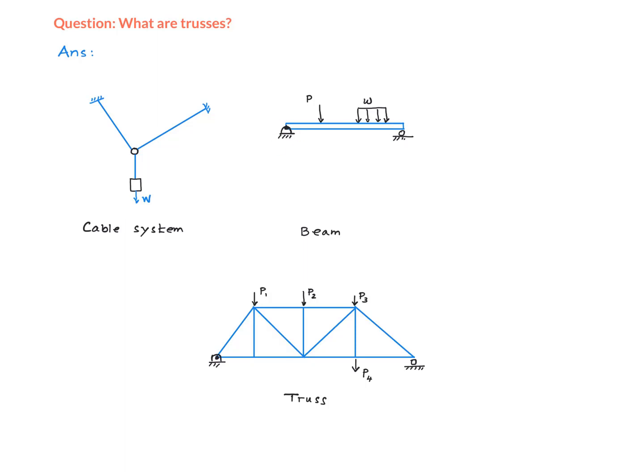To design the beam, we have to find the support reactions and the internal forces at all the points on the beam. We treat beams as rigid bodies, so as we go from a particle to a rigid body, in addition to the linear forces, we also need to consider moments. So in solving this problem, we not only satisfy the force equilibrium equations, but also the moment equilibrium equation. In general, the internal forces at any point on the beam consist not only of the axial forces, but also the shear force and the bending moment.